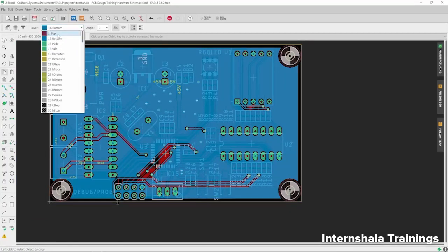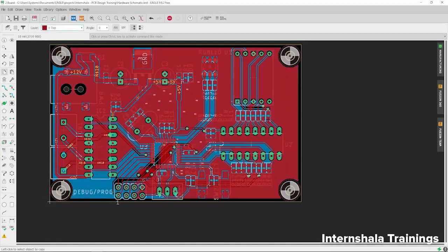So that's how, if you place multiple wires on your PCB everywhere, try to place them in the right manner. It should not be like you are placing too many wires on the PCB. Otherwise, the return current for this IC would have gone like this and then towards this point, following this path.